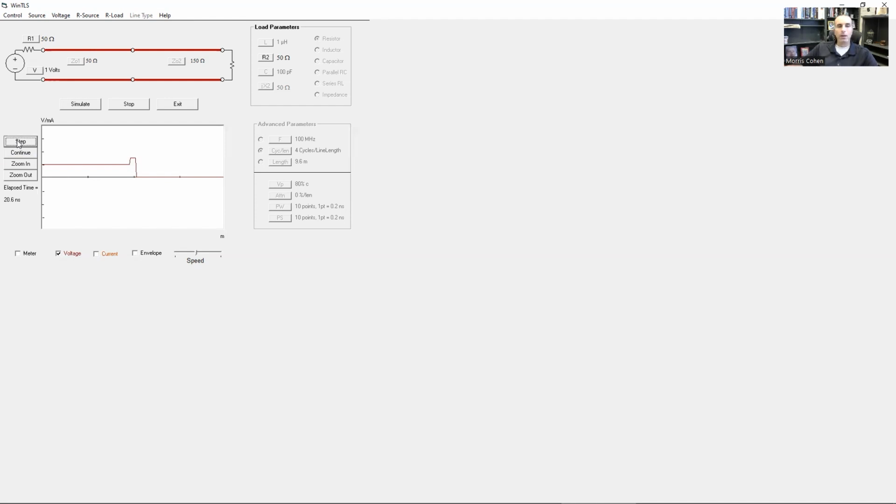All right, so here we go. You can see that reflection has happened. The wave that's now propagating backwards on transmission line 1 has half the value of the wave that came in. These tick marks are 1/2 volt long. So this is a 1/2 volt here, and that's about a 1/4 wavelength of the second wave built on top of it. The wave that's propagating into the second transmission line is the sum of both of those.